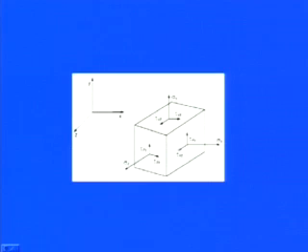So now we can simply show the triaxial state of stress in a generalized way in this particular figure. As we discussed, we have three mutually perpendicular directions x, y and z, and in those there are always two mutually perpendicular stresses. These are the axial stresses sigma x and sigma y, and we have tau xy. If you want to express those in tensor form, which has 9 components, we can show all of them on a generalized unit cube.